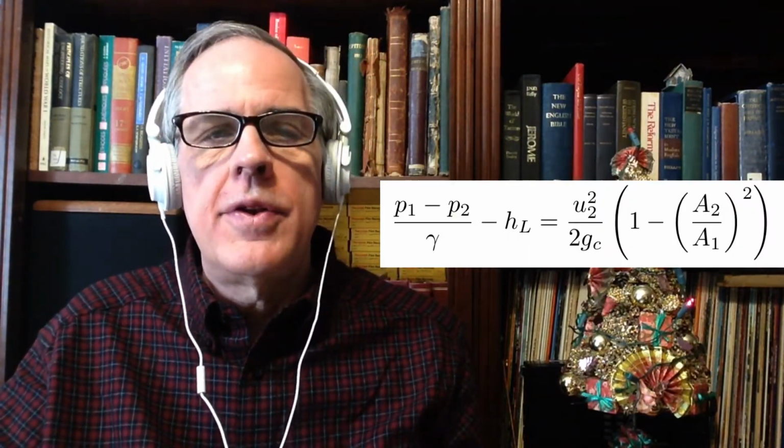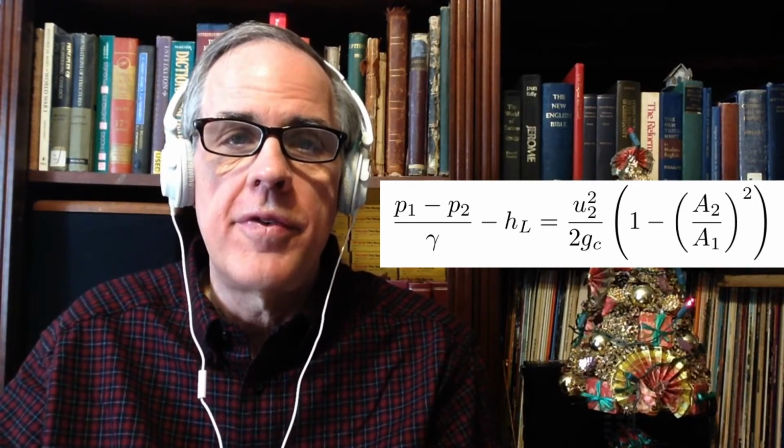We do some other math, and we end up with an expression of what we would anticipate the change of head to be across, in our case, a flow device. We're actually aiming towards flow devices. The change of head is basically the change of pressure across the device divided by the unit weight of the fluid. So we do some more rearranging and math, and we end up with a situation where the flow is a function of the geometry of the system, the head loss we measure, and the head difference. The delta H is the head difference, and the H sub L is the head loss across the device, because actually you could get a head difference just from other factors.